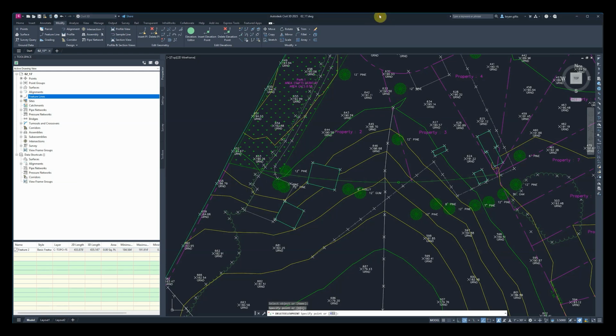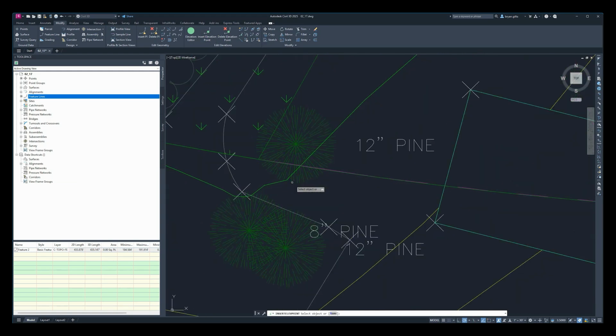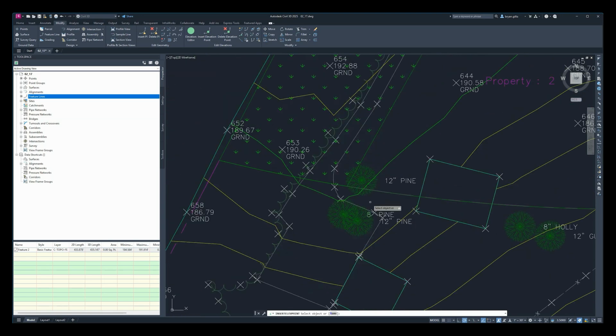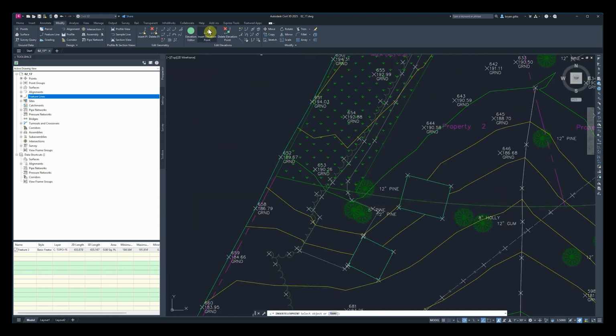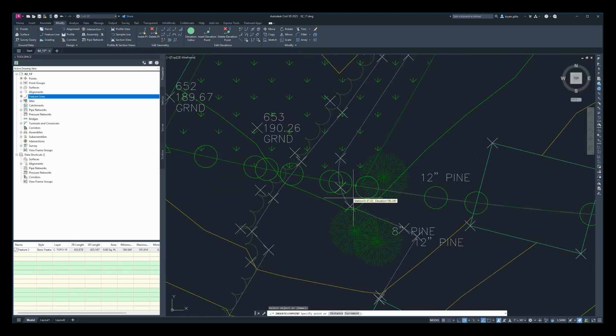All right. Focus. So now that we've gone through and deleted points, let's look at inserting elevation points. We have this cluster of pine trees over here, so let's zoom into that area, and we see our feature line here. Let's click Insert Elevations up here in our elevation pane, come down, and select our object. Now we see all of our existing points have highlighted large green circles on them, and we have this moving small one. This is where we're looking at creating a new station point.